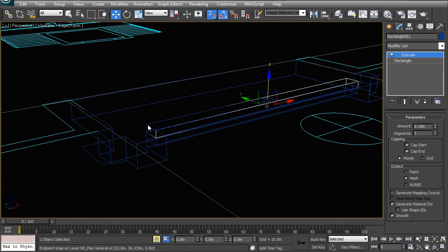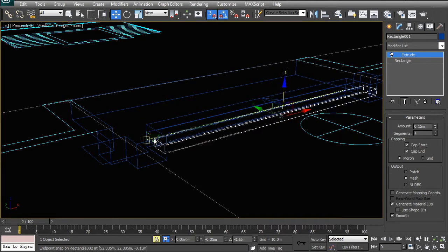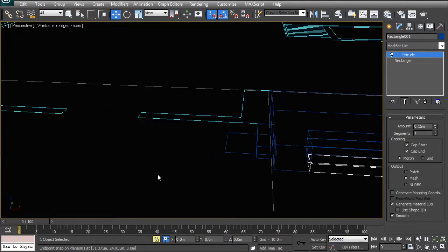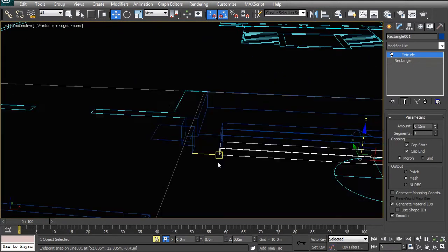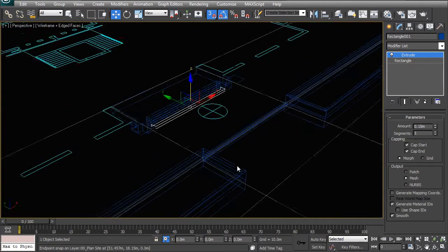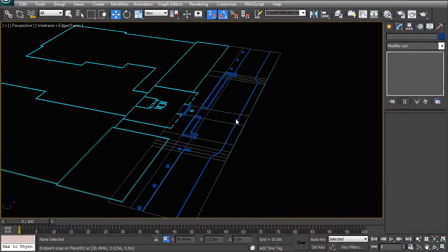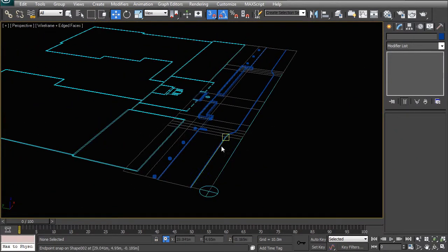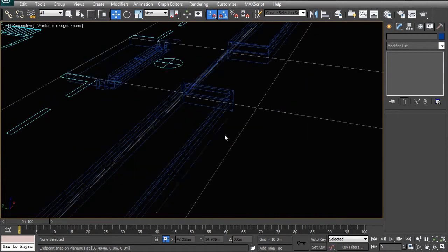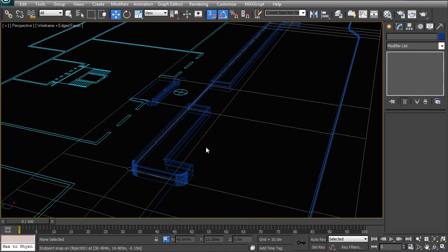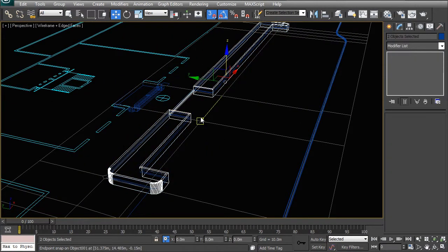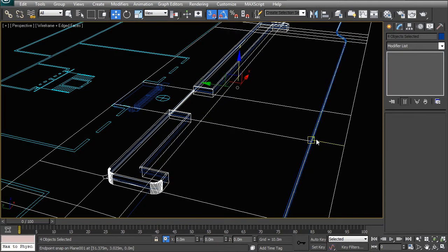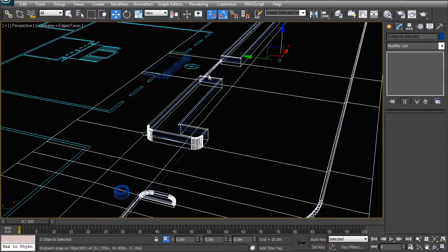and I'm going to make a copy, and then this copied version, I just hold down spacebar to do a selection lock. And I'm just going to move that down. You'll see that it's actually below the road level right now. So what we need to do is we need to move down the road object that we created earlier. So we're going to move that down by the 450. So we can go and select the road, the pavement edges that we created earlier, making sure not to select any of the CAD geometry.